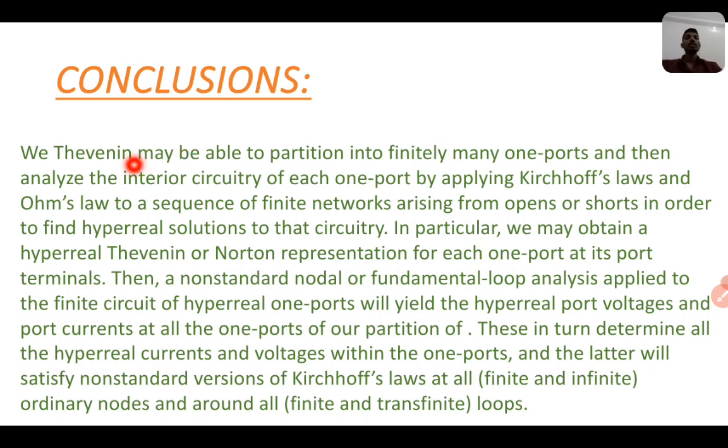Conclusions. We may be able to partition the network into finitely many one-ports and analyze the interior circuitry of each one-port by applying Kirchhoff's law and Ohm's law to a sequence of finite networks arising from opens or shorts in order to find hyperreal solutions to that circuitry. In particular, we may obtain a hyperreal Thevenin or Norton representation of each one-port as its port